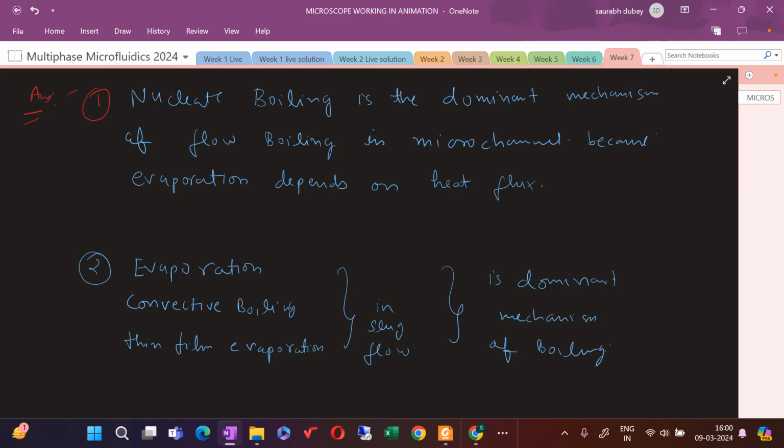If you remember, in the conventional channel the nucleate boiling dominates in the bubbly and the slug flow patterns. Why? Because the enhancement in the heat transfer arises from the evaporation of the thin liquid film underneath the bubble during its growth, and strong mixing in the bulk flow due to bubble agitation after it leaves nucleation sites. Also, the bubble generation frequency, departure diameter and the diameter range of the active nucleation sites increase with the heat flux and the pressure.